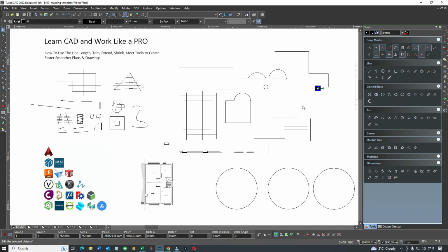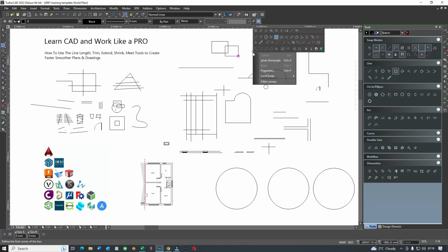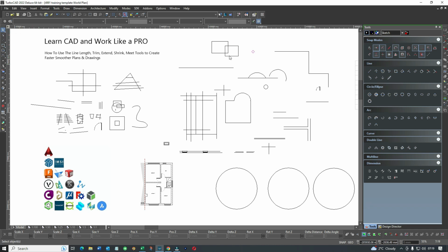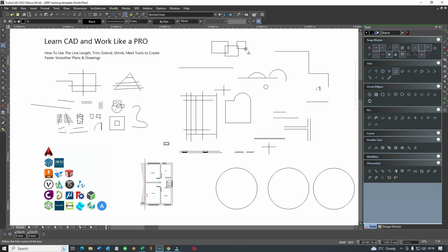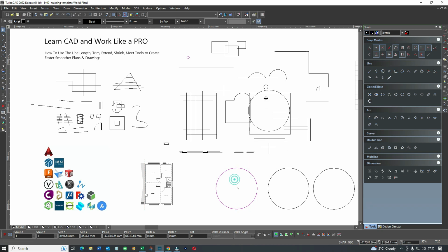You understand? So we'll go through that again to make sure you get it. I'm drawing lines. I could be drawing squares. I'm drawing a square, drawing another square, and I want to grab this circle to add to it. So normally, as I said, what I would have done was go to the select tool on the top left. I could have picked it up on my right click menu, which is over here, select, and as you can see, suddenly it's highlighted. But let's go back and draw another square. I need to get a circle, so before I can grab it I need to go into select mode. So this time I'm going to hit spacebar. Now watch how it changes here when I touch spacebar. Touch spacebar, it automatically changes to the select tool. So I can grab my circle, drag it up.